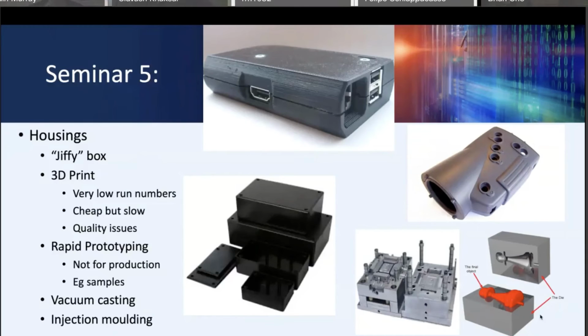The problem here is that the component that you're producing is extremely cheap. The cost to run it isn't. When you want to do a run of injection molding, you're looking at tens of thousands of devices that you would need to produce before the manufacturer would even turn the machine on for you. So it needs to be very, very, very high.